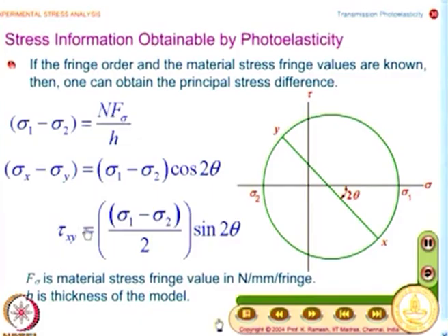If you remember and recall, one of the very important problems in engineering is I have a 3-point bend specimen. I want to find out what is the variation of shear over the depth. I said when I go closer to the point of loading, though you have read in your simple strength of materials course that shear varies parabolically over the depth, this is no longer so when I go very close to the load application point.